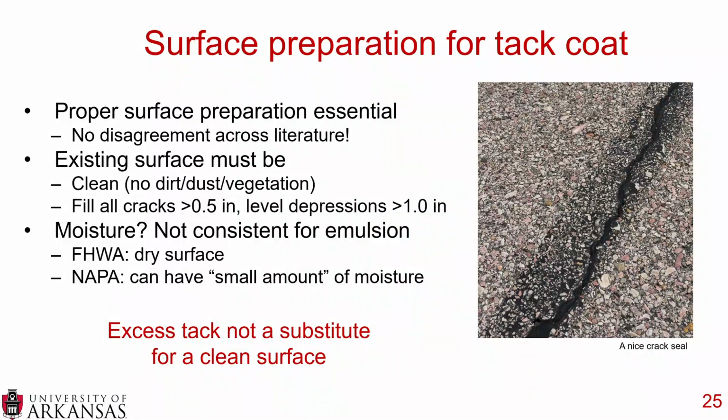Now, I do also want to say excess tack coat is not a substitute for a clean surface. If you have a dirty surface, you can't simply throw more tack coat on there. That will not work. It'll create a slip plane. The tack won't behave properly. It may bleed up into the surface. So you need to properly clean the surface, and the surface structure must be properly prepared.